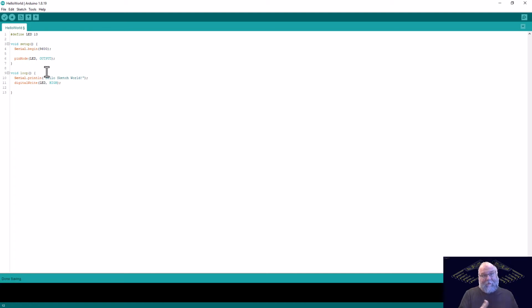Now, just for fun, we want to make it blink. So let's do a delay. Let's make it 250 milliseconds. And then we're going to do another digitalWrite to the LED, setting it low. And then we'll do one more delay of 250 milliseconds.